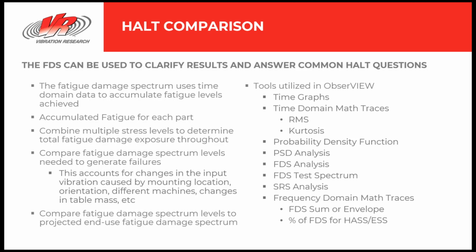What we can do is calculate these values and compare them across different step stresses, accumulate them across multiple step stresses, and also compare machine to machine, location to location, etc. As you're running your testing, you could have sensors mounted at each product and be accumulating damage for each product to ensure that your failures are occurring maybe not at the same time, but at the same relative damage levels, thus minimizing the statistical variation between your samples when you're solely basing them on time.